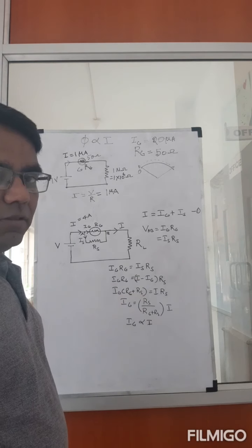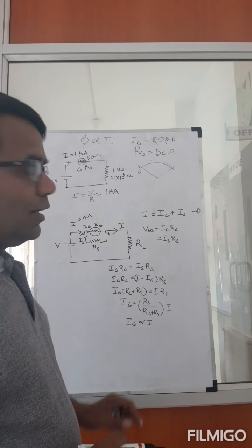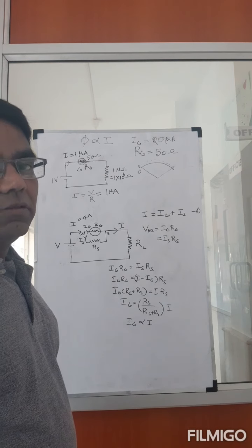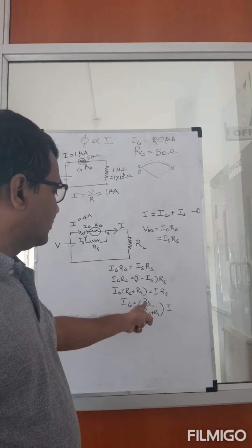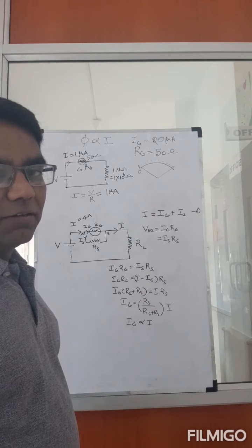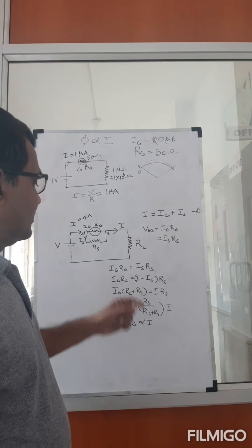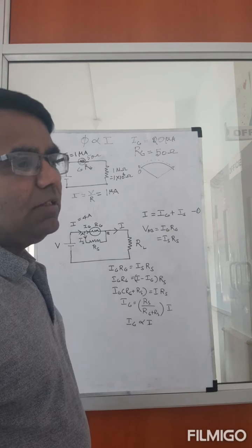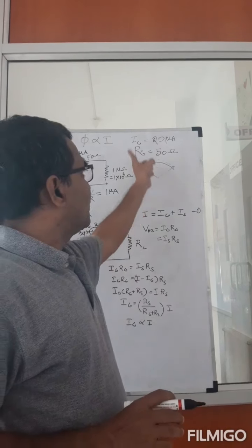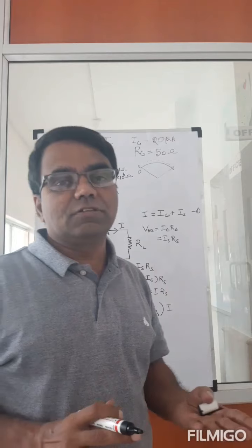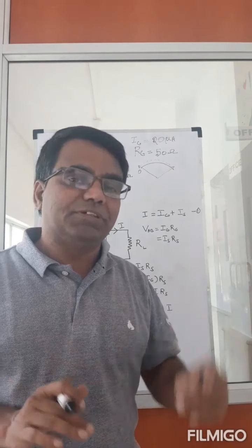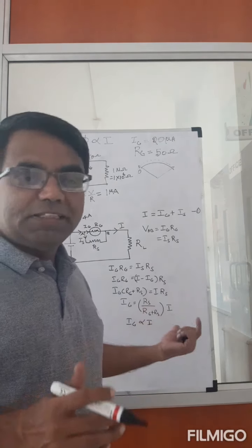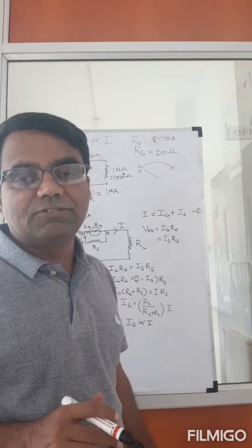Because using this, I can theoretically use this galvanometer to measure any range of currents. All I need to do is get the appropriate resistance to connect in parallel. So now let's see. Here, like I said, 4 amperes is flowing. Let us suppose that I want my galvanometer to give full deflection when the current in the circuit is 10 amperes. Then what should be the value of my resistance, RS, the shunt resistance?